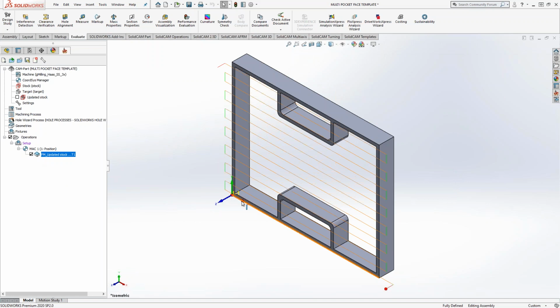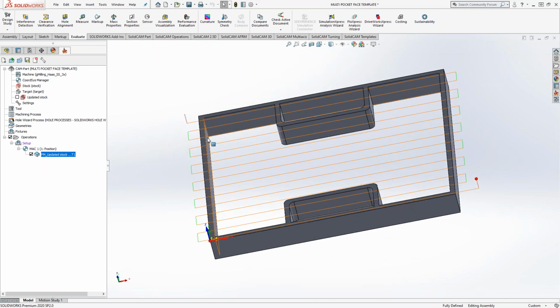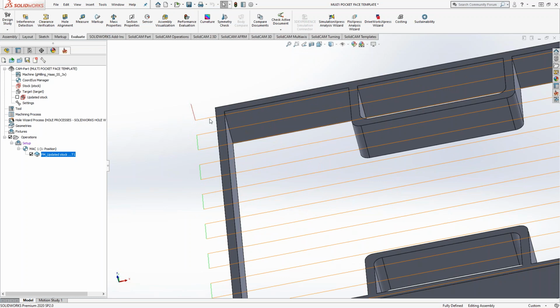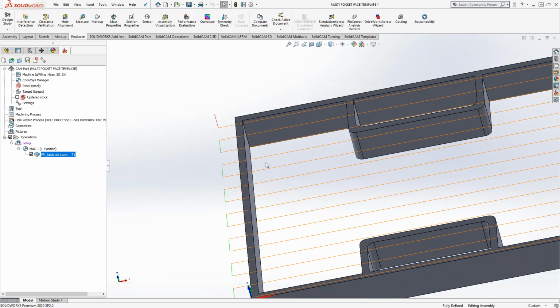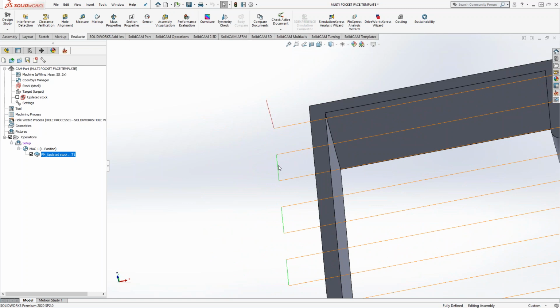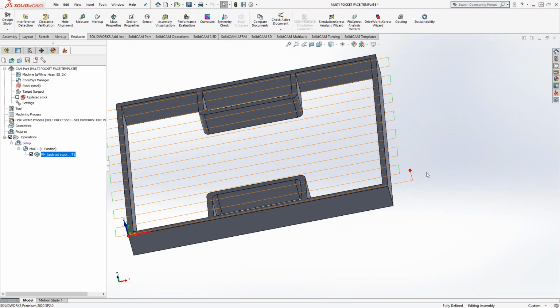When you look at your tool path, the wireframe, you have basically 3 colors that make up your wireframe. The color that you've defined for your tool, so in this case I have this kind of darker orange color, that's my engaging material feed move. The green move is a feed move as well, but away from the part. It's non-engaging, or at least that's what this thing is assuming by its stock definition. And then your red color is your rapid.